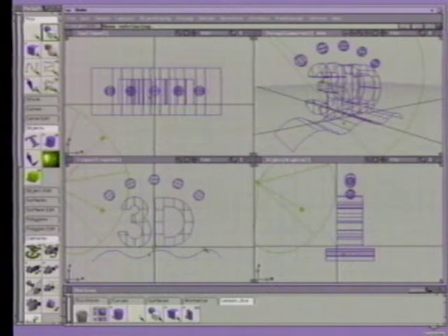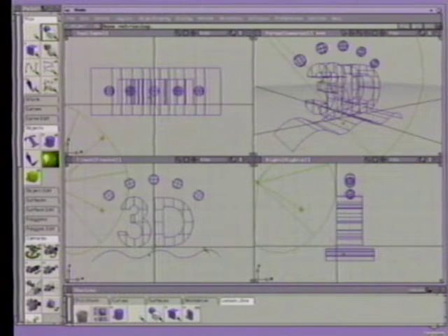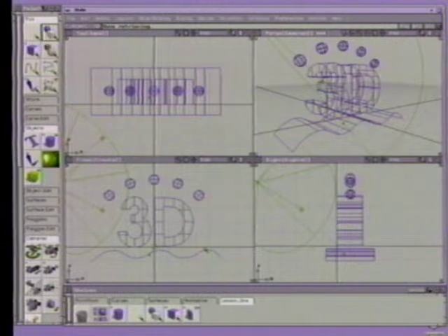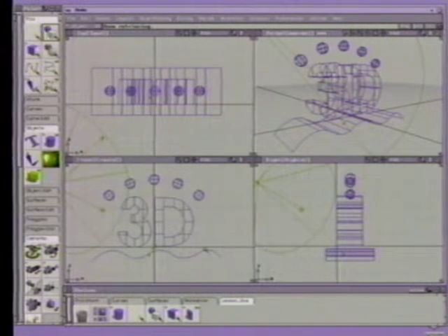You may note that while the curved surface seems to sit on the ground in the perspective window, in the front window it is below the ground level. When positioning objects in 3D space, using several views in combination is the best way of ensuring that you are positioning your objects properly. You are now going to change how each window views the objects in your model.